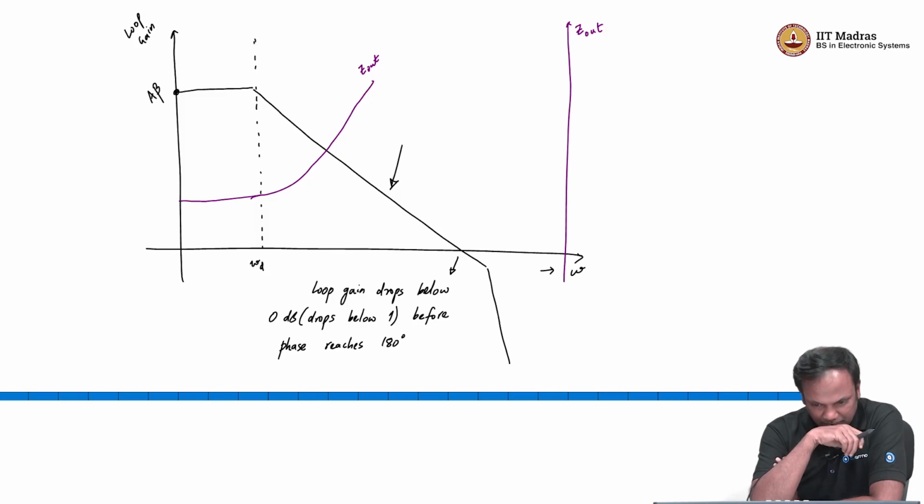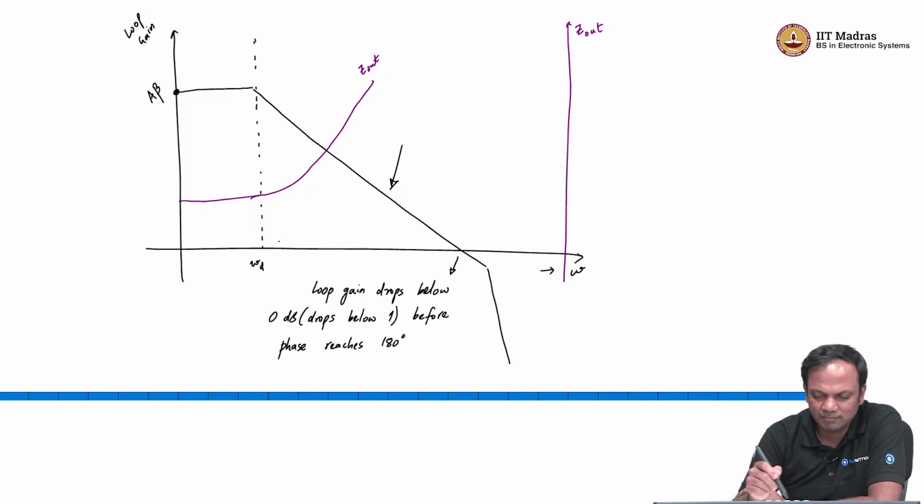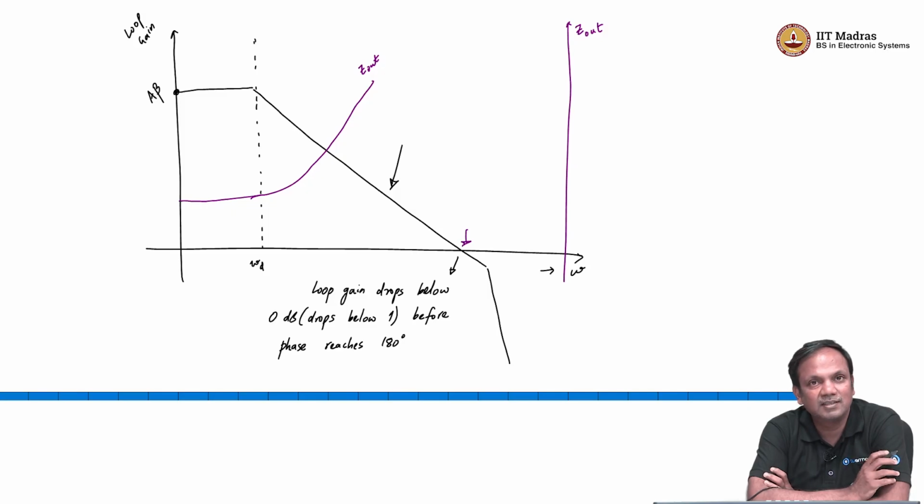So, now let us say somebody says, okay, my bandwidth, which is this point here, is 100 kilohertz or 200 kilohertz, right. Then somebody might wonder, what happens if I use this LDO for a digital application where my current is in the megahertz? I am assuming this is a voltage source which will present very low impedance at high frequencies, right.